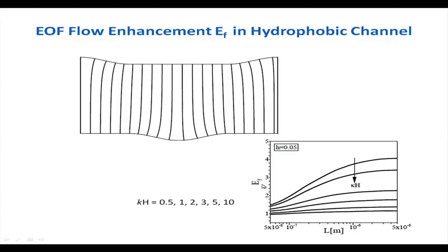This is the ratio between the ordinary planar electroosmotic flow and the modified one, that is with the superhydrophobic surface. What I find is that sometimes more than 4 times enhancement occurs when we place the grooves within the channel. That means the intrinsic slipping effect is considered. That is why superhydrophobic and hydrophobic surfaces in microchannel situations are quite important. So I just gave some introduction to how the transport can be enhanced by considering hydrophobicity at the wall. Thank you.